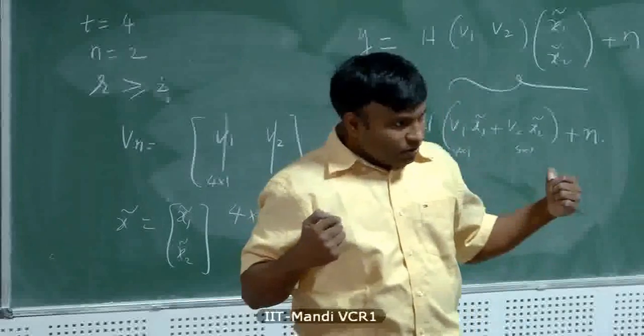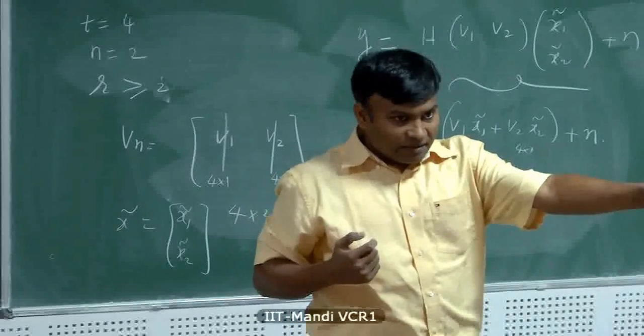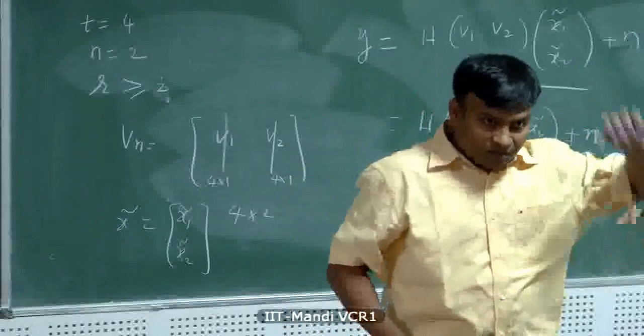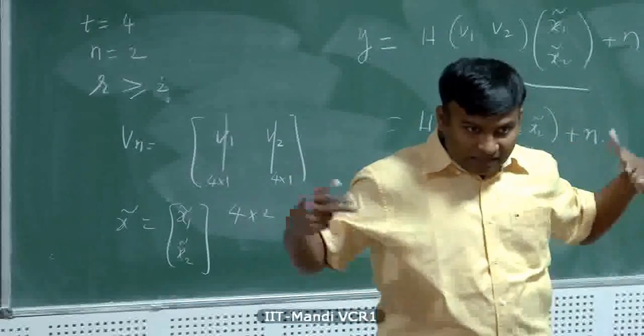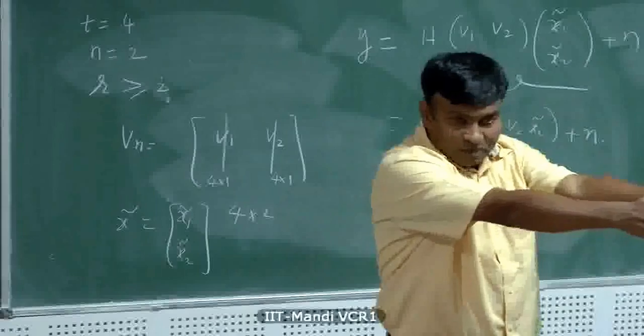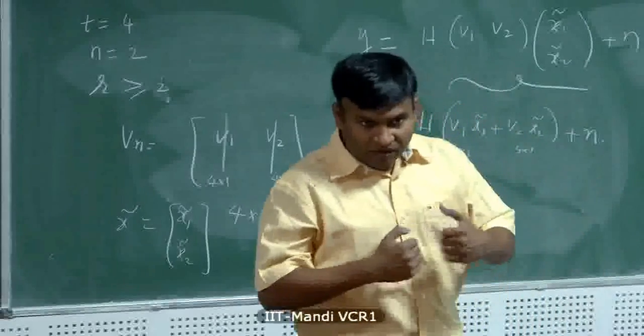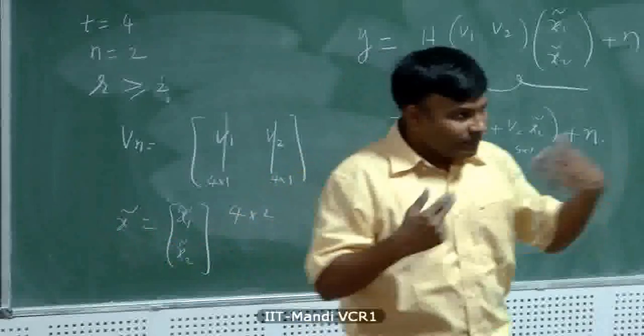So you can measure the path gains from each transmit antenna to the receiver, put a spatial matched filter, and then you put a strong beam towards one receiver. And as the number of transmit antennas increases, the beamforming gain increases.